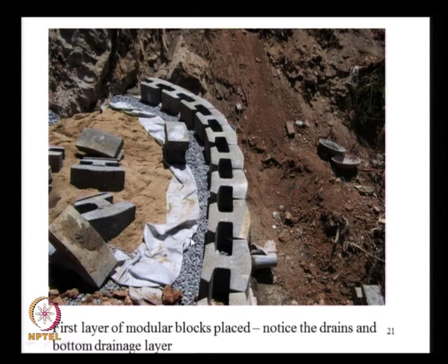And this is how the entire construction started. The construction starts by leveling the ground and preparing the base, and in this particular case, because the subsoil was hard stratum, hard rock at a very shallow depth of about half a meter, there was no ground preparation required. At the bottom you level the ground, and then at the bottommost, this stone aggregate